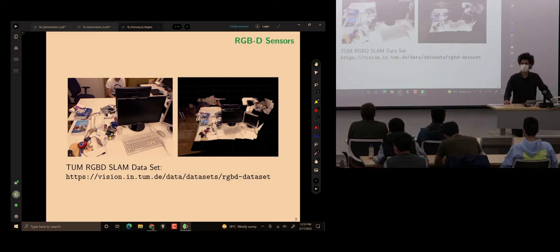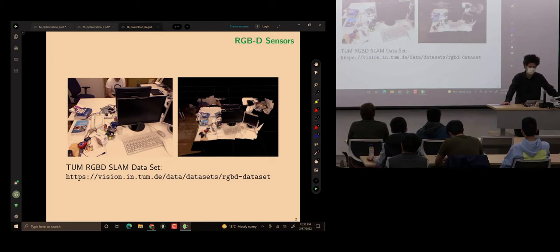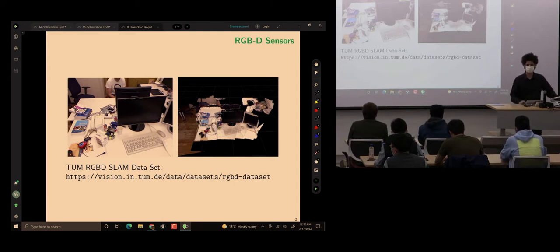In this lecture, we particularly focus on a point cloud that we might receive from different types of sensors. And these sensors can be RGBD cameras. RGBD cameras are a type of depth cameras that will give us 3D points, depth of a point, as well as the familiar RGB image that we see. So for every RGB value, we have a depth value. And this one-to-one correspondence makes it very nice because ideally we get a dense depth map.